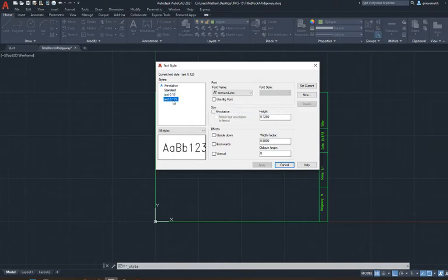Now this is simply defining the height of the text. So we can see down here what the text looks like. See, if I go to standard, it looks very different. That's because both of these are in the Roman B font name, so make sure to choose this font. The width factor for both of these is 0.8, which is pretty straightforward.